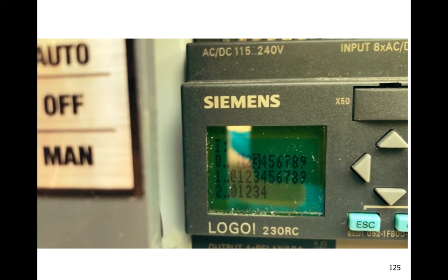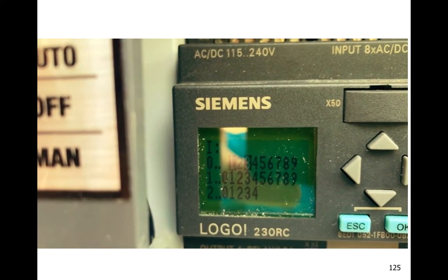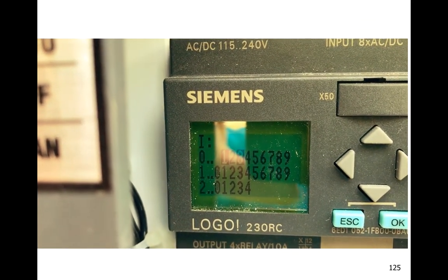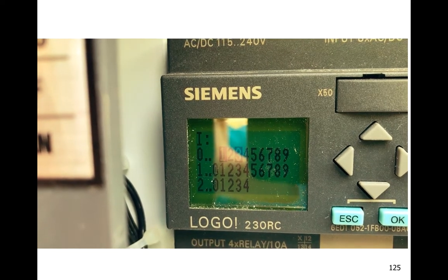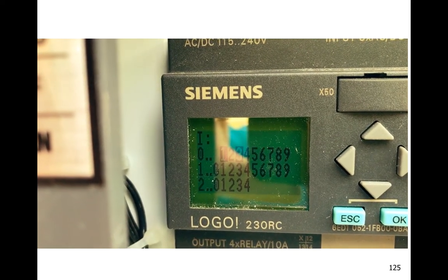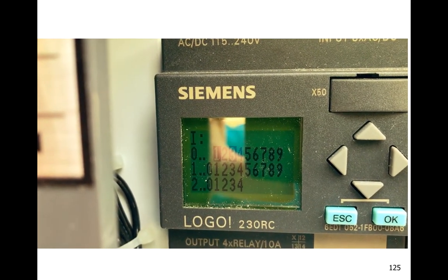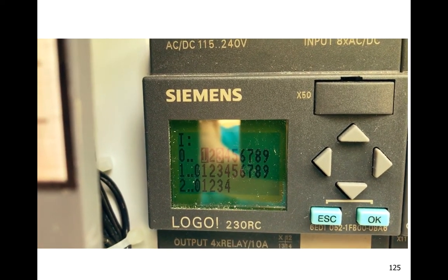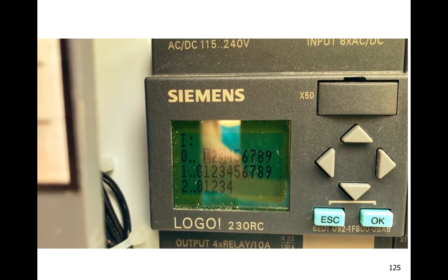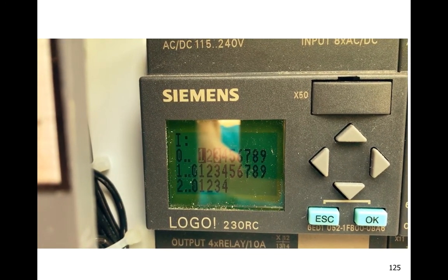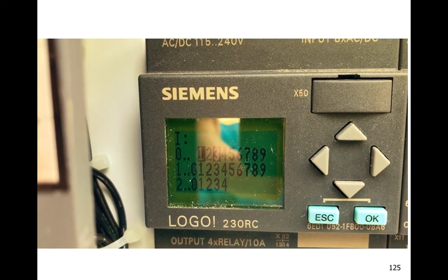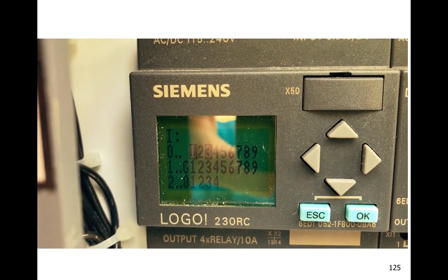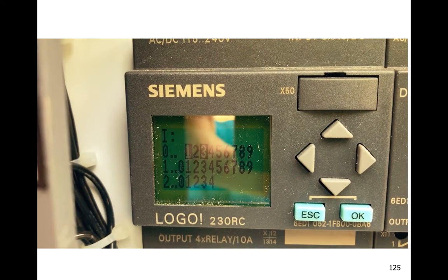And here we see we've got the number 1 input and the number 3 input illuminated, which are backlit, which means the bottom float for the recirc is up, and the bottom float for the discharge or Oscar tank is up as well. When the system is in operation, we should always see the number 1 backlit. We never want to have the liquid level go below the bottom float on the discharge side.